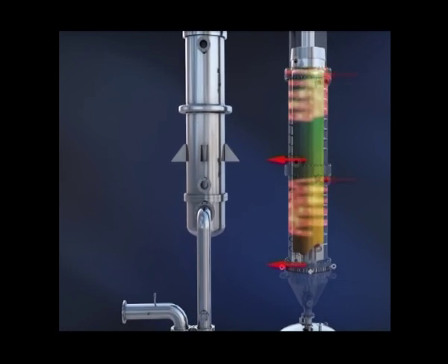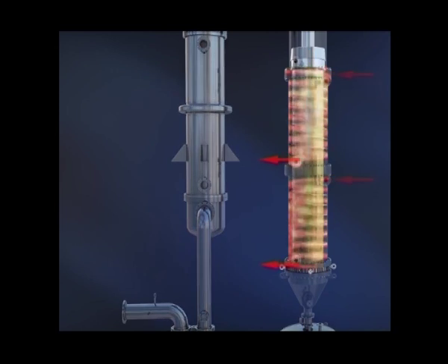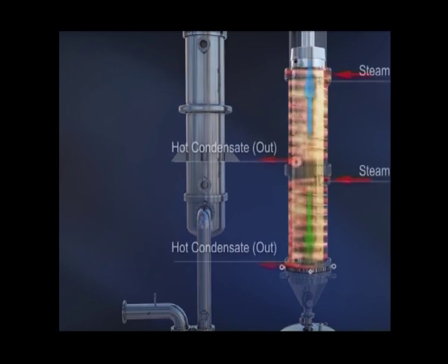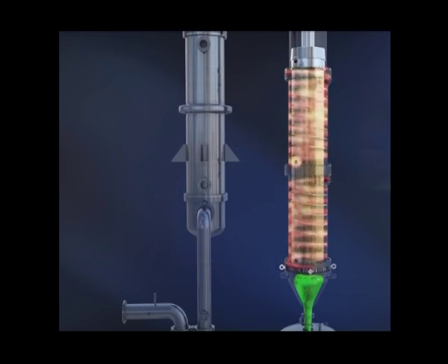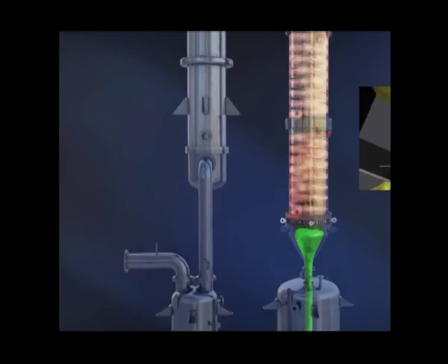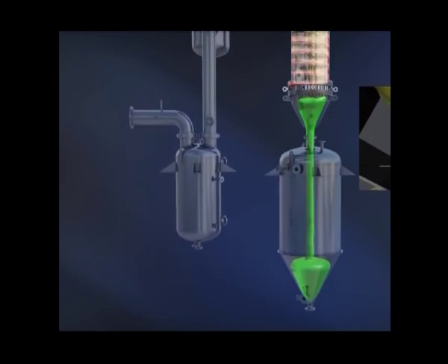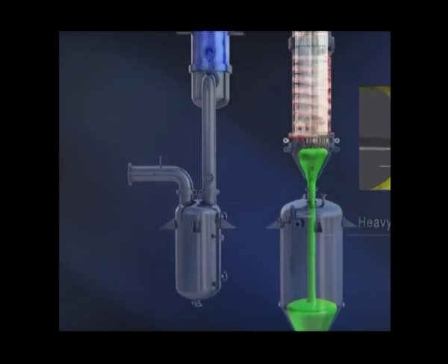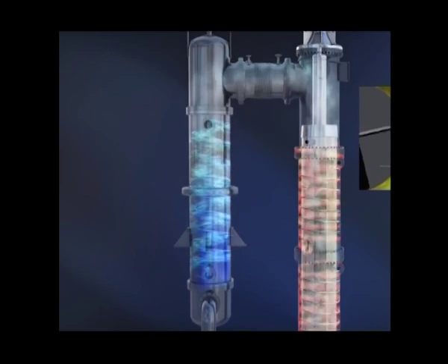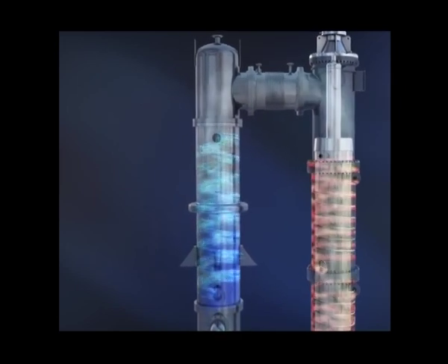With some modifications, these are also called scraped surface evaporators. They are best suited for heat sensitive viscous juices such as mango pulp, gelatin and even antibiotics. Feed enters at the top of the jacketed section and is spread out into a thin film by the vertical blades of the agitator.